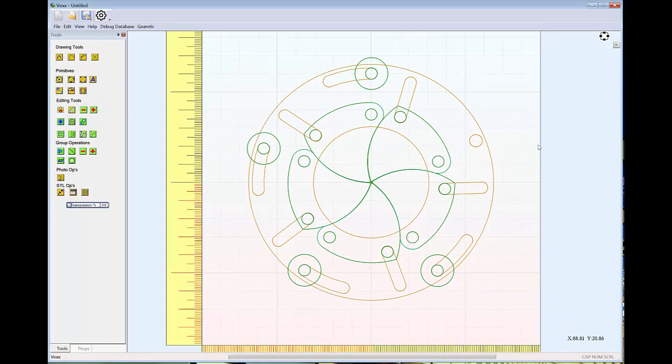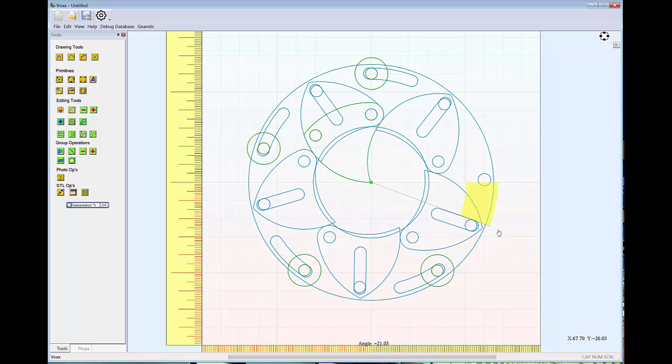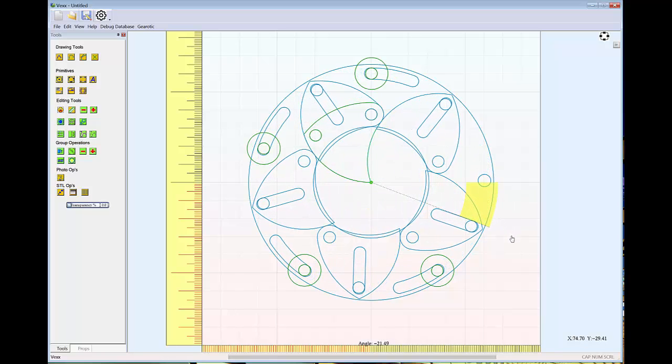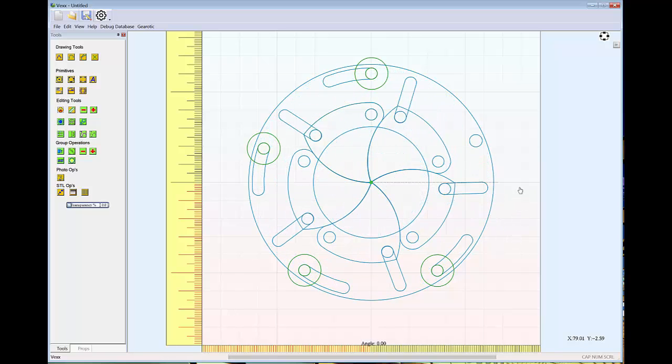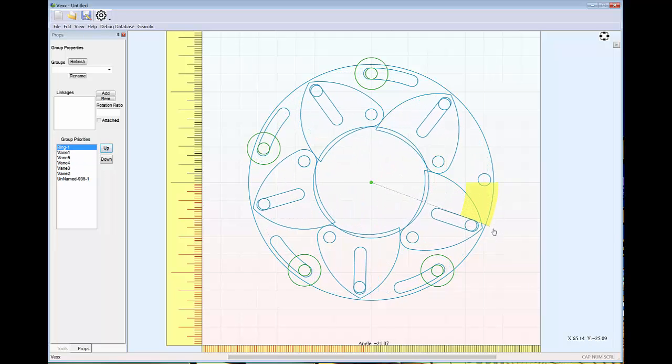And that's it. We now have our back plane, which is these 4 dual level pins. They come up to just under the ring and then follow up with a 1/4 inch pin through the ring. The ring is driven on the slot on the center of that pin, and we have a device that runs. But you'll notice we're back to having vane 1 drawing on its own. And this is because we've regrouped and the ring is at a low priority again. We're going to move that priority up, and then everything will simulate normally.